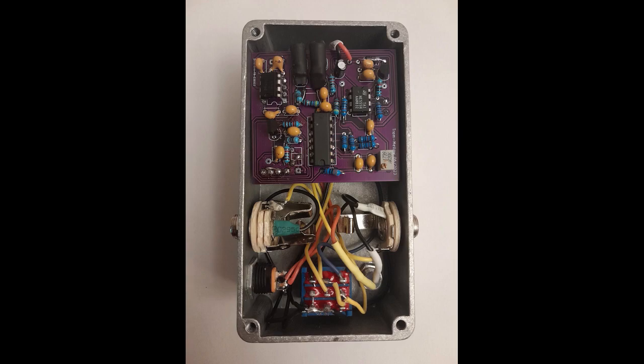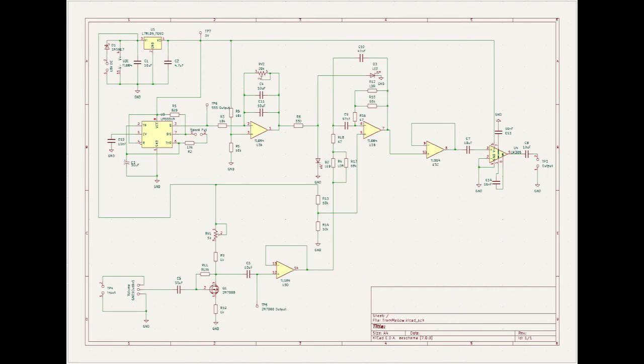Prior to routing components and ordering the circuit board, a physical mock-up of the Tremolo effect was breadboarded. The behavior of the circuit was exceptional despite the inherent parasitic capacitance and inductance that exist in prototypes. Despite fully assembling one pedal, the design team was unable to have the end product function as an acceptable tremolo. Test points were included on the schematic, and through troubleshooting the circuit board it was discovered that the signal was lost at the output of the filter.